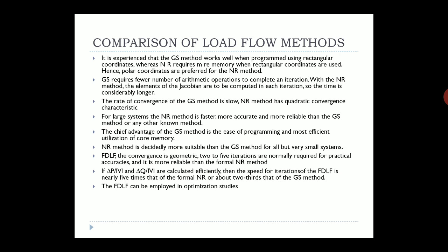You need to understand these load flows are utilized, and nowadays computers constantly take in values from the different buses and, at regular small intervals, calculate the load flow in order to provide the operator the condition of the power system. So in order to know the condition, the data collection and the calculation should be faster. Most of the time these fast decoupled load flow methods are used.